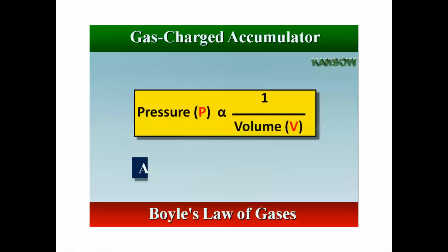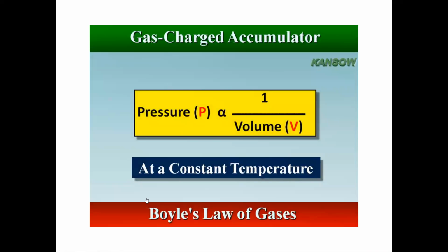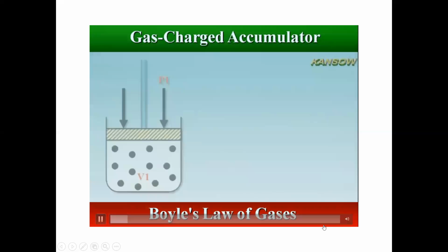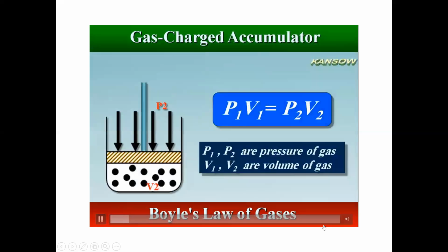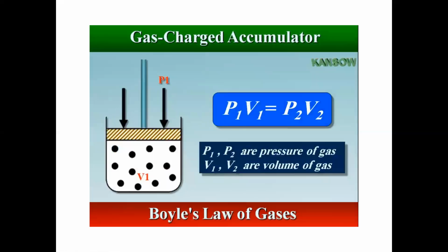The gas-loaded type hydraulic accumulator. As I already told you, this gas charge accumulator works on Boyle's law, according to which the pressure of a gas is found to vary inversely with its volume for a constant temperature process.